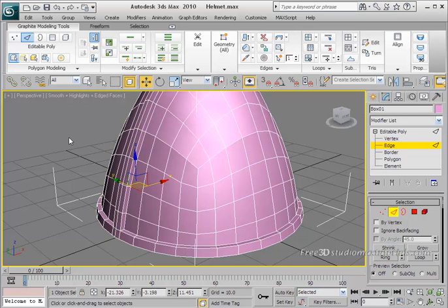Okay. Now on the modify selection panel, click the ring tool. Just click on that. All edges parallel to the one you selected are also selected automatically. Now on the loops panel, with the hold of your shift on your keyboard, click on connect.